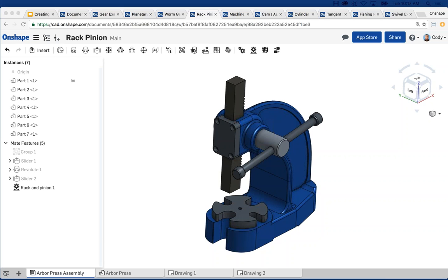So, can you make a chain link assembly? Can you make a chain link at multiple degrees of freedom due to pivot points, but travel along a sketch path? You can't define it as traveling along a sketch path, but I will show you in a moment where if I have faces to reference, I can, for instance, like a groove cut into something, I can tell it to follow this path. And if my pieces have multiple degrees of freedom, they're free to move within that travel of the path. So bear with me. I do have an example of following a path. It's not a sketch path, but it may give you something similar to what you're looking for. So give me just a moment.